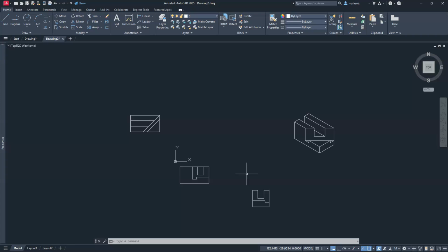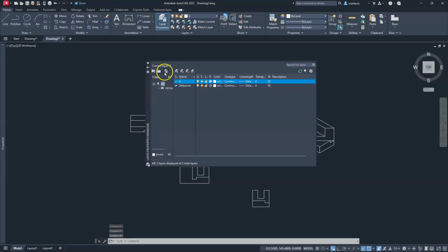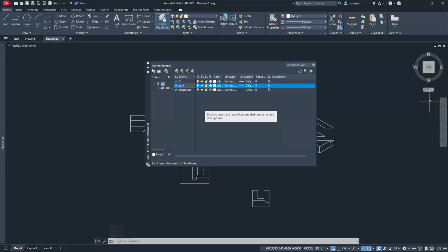Before I do that, I'm going to put some hidden lines and things of that nature on our drawing here, just so we know where everything is, okay? So let's go ahead and create a layer. We're going to create a couple of layers here. The first one I'm going to create is going to be a center layer. In this one, we don't have any center lines. It's just good practice to keep doing that, or making sure that I create one. But we do have a hidden layer, right?